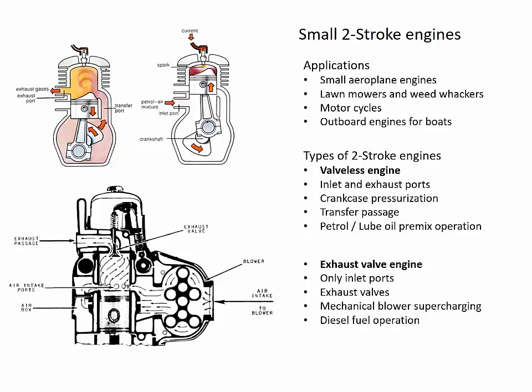Also, what's of interest in this diagram is the mechanical blower, the supercharger. So when the crankshaft rotates, either by means of a gear drive or a chain drive or a belt drive, the supercharger will draw in air from the atmosphere and actually pump the air into the inlet spaces, the scavenge spaces as we would know them. And then when the piston moves down, the inlet ports are opened and the pressurized air can make its way into the cylinder.